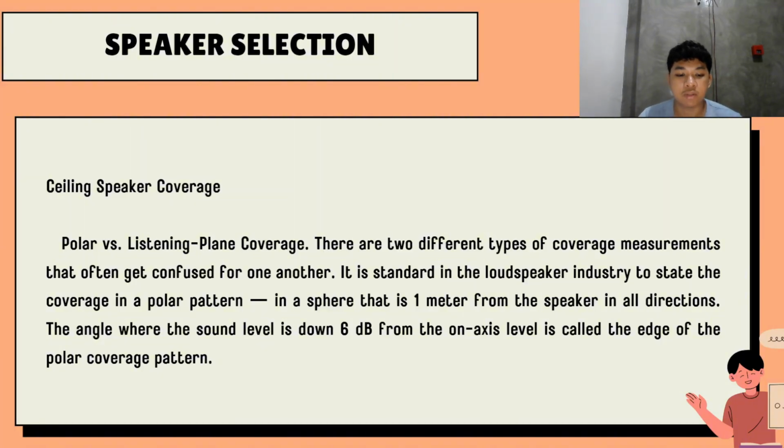It's a legitimate specification, but it does not represent what the coverage will be over a flat listening plane in any room, because it doesn't take into account the difference in distances that people are from the speaker, for speakers projecting from a ceiling into a flat listening plane. The sound has to travel farther off axis to the sides than it travels on axis directly below the speaker, resulting in a much greater drop off of sound level off axis.